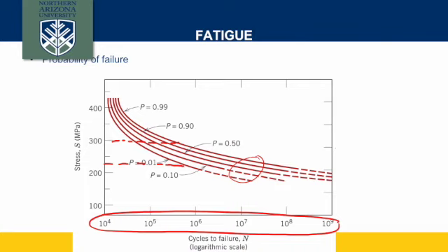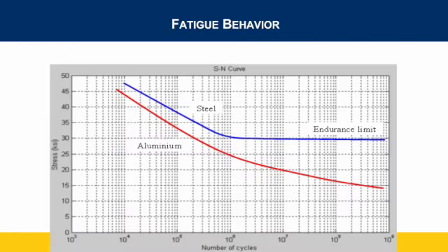We create two exact samples, but we may have different size pores or voids in them just from how we processed them, so we get variation. We typically test many samples and get an average and a standard deviation. The material should fatigue down to this level, but it could last as high as this or as low as this. That's the standard deviation I talked about in the last virtual lecture.